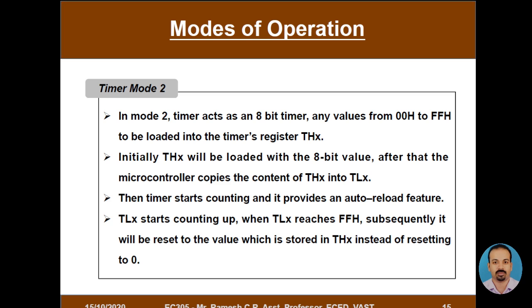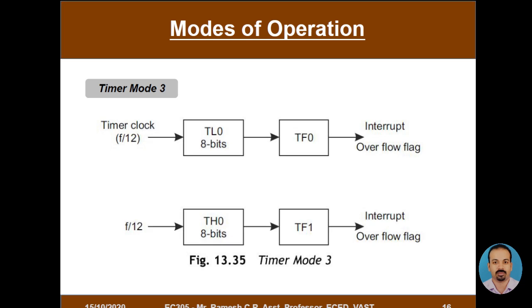Here we need not load the value to the counter register deliberately, but we need to clear the timer overflow flag using some software code.